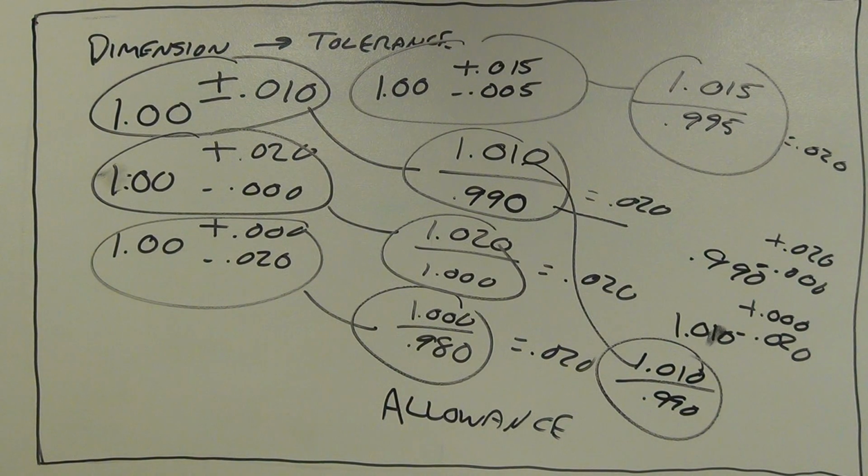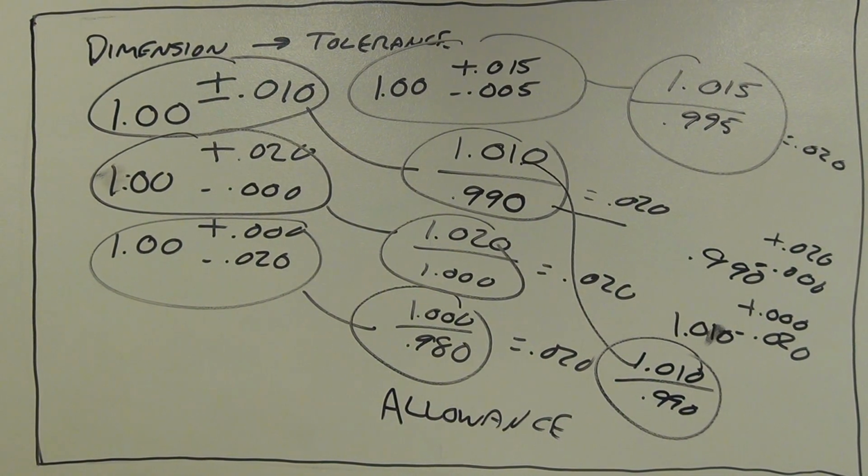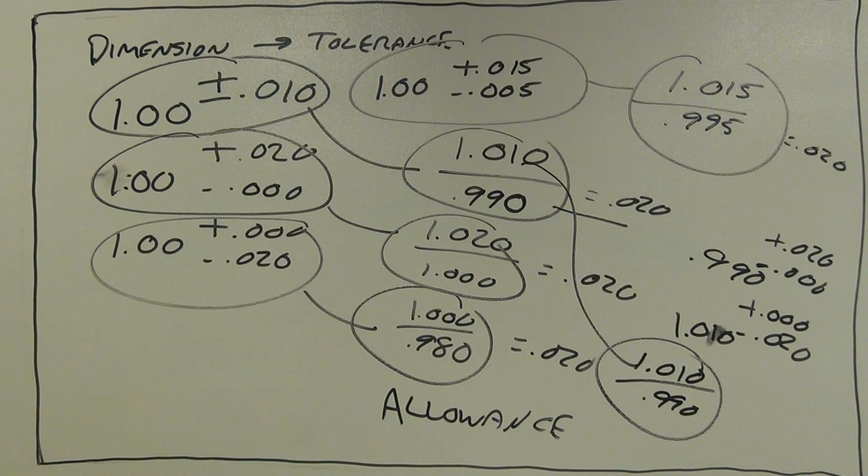depending on how the dimension is expressed, you get a certain amount of tolerance, and it'll list it. And it'll say if the dimension is expressed in 1 decimal place, you get plus or minus 50 thousandths. And if it's 2 decimal places, you get plus or minus 25 thousandths. And 3 decimal places might be plus or minus 5 thousandths. I am no big fan of default tolerances. They cause a lot of problems.